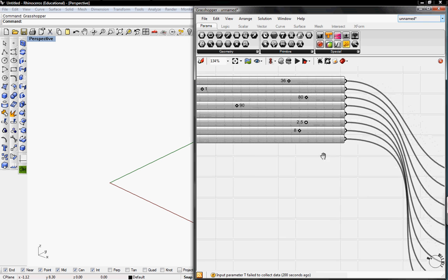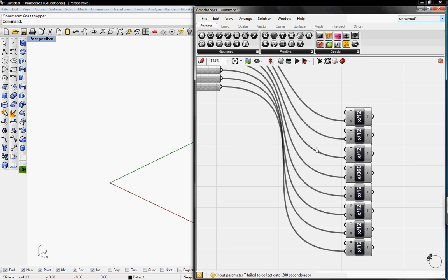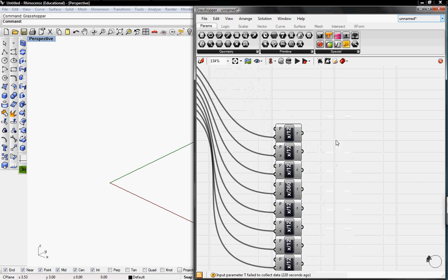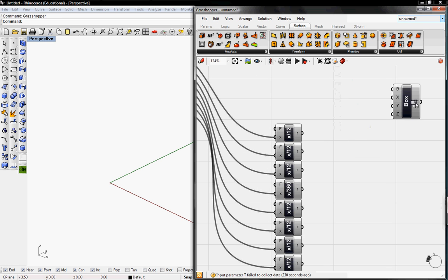And then you guys are going to need a one variable expression for each slider to convert into inches in Rhino, since we usually use feet in the Rhino models. So everything is going to be x over 12 except for the degrees, which is going to be x over 360. And you'll see why we need to divide by 360 as the tutorial goes on. So to create our door frame, we're going to need a box in surface, under primitive, interval box.